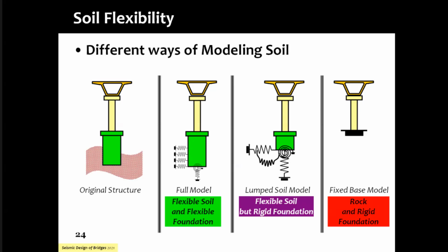The second one can be used only when your foundation is very rigid. So if you're having pile foundation, it's not on. In the case of well foundation, definitely this is a possibility for you. But you will, in the early years of your life, be benefited by modeling both the full model as well as the lumped soil model, and see what are the differences for different parametric changes, especially soil properties and the aspect ratio of the well.